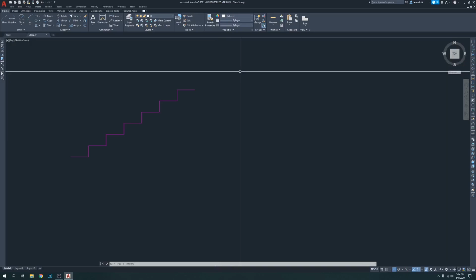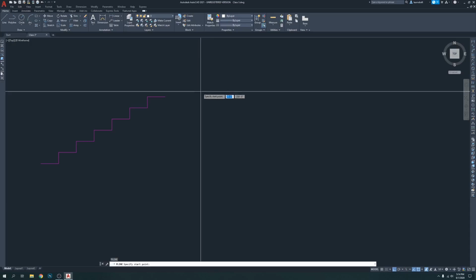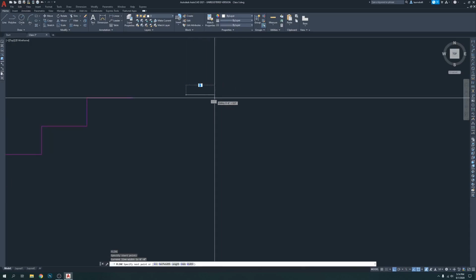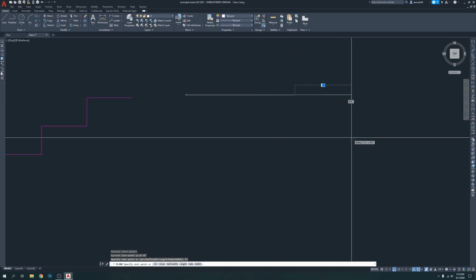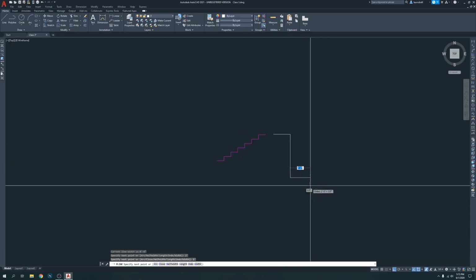it. So let's say you want to draw a box. Now to draw a box, if you want to draw it by polyline, for some reason, sometimes you need to draw by polyline. So you're going to PL, enter, click here. Let's say your box is 2 feet, so you type 2 and feet, which is left of the enter button, enter, go down, make it 5 feet, enter, go.